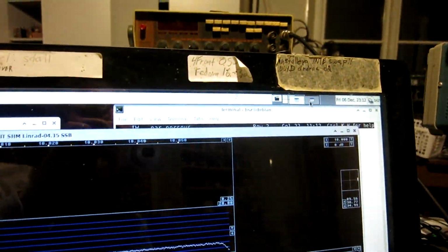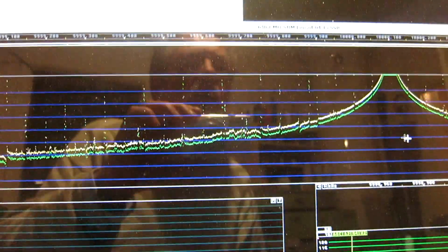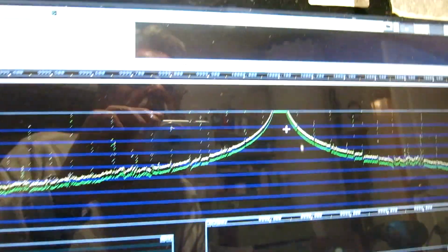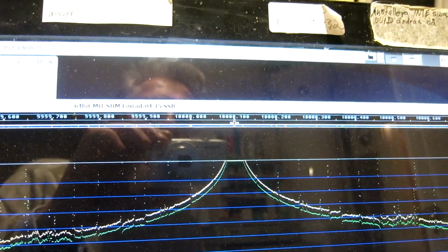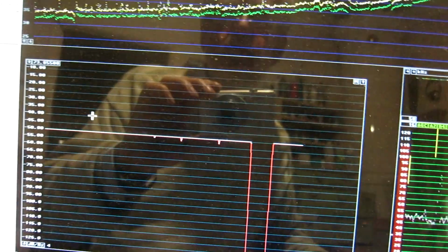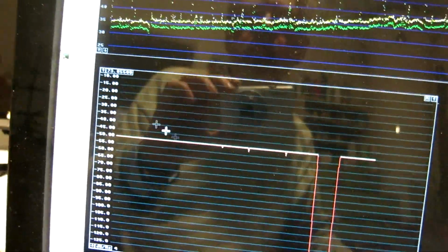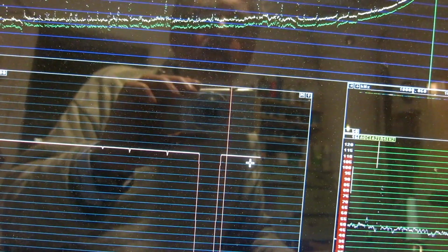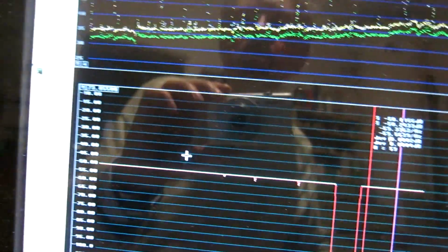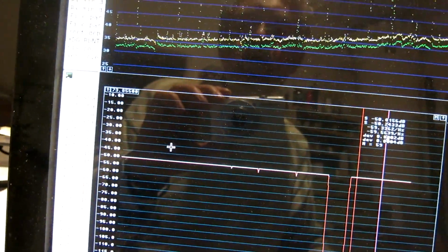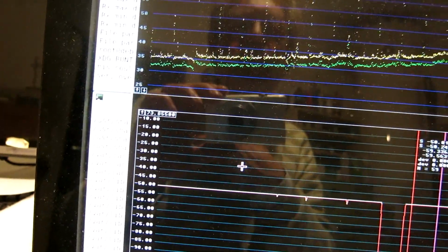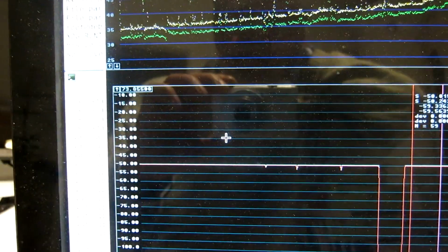Then I go to the other window here, where I have the system with the interferometer. And here I have the signal at 100 hertz, about 10 megahertz. So I put that into the filter and look in the graph, and here you can see the level. And it shows minus 50, which means this scale is now properly calibrated. And I haven't touched anything, it's the same settings that I had while doing that measurement.